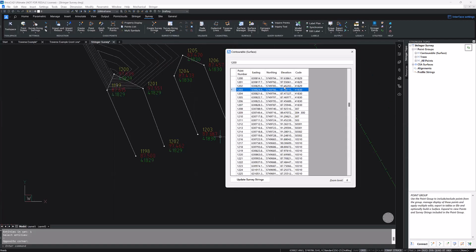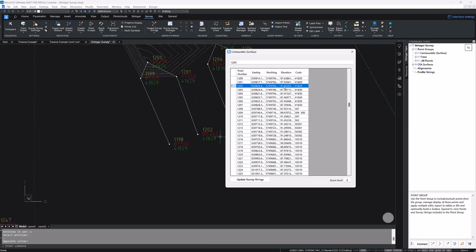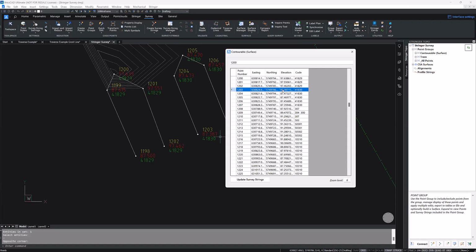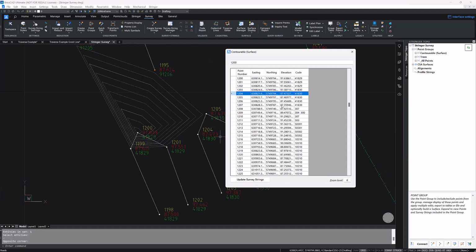I can do all these edits, and let's say you have a job that numbers in the tens of thousands ranges in terms of points. Now, if your computer is having issues with this, it's an older system and it's struggling with the large point numbers, what you can do is use this to do a large amount of edits to your survey and then apply an update after you've done the edits. Because you're not doing any heavy lifting, all you're doing is setting these changes to occur.